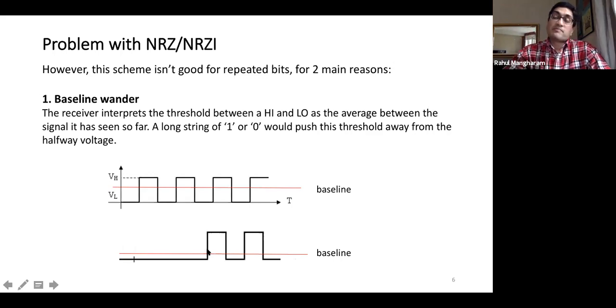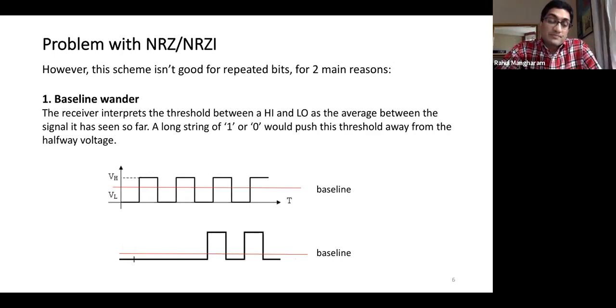But then you can say, look, in theory, I'm going to just be comparing, is this voltage above or below? If I have 0 to 5 volts, is it above or below 2.5 volts? But in practice, you're actually comparing to what is an actual value in a capacitor that you can have, right? So you would always want to have this, like how we did with our ADC. We're always trying to compare to some generated voltage of 2.5 volts. Here, because these circuits operate so fast, much faster than an ADC can generate a voltage, they have to use the average of the value based on the signal.